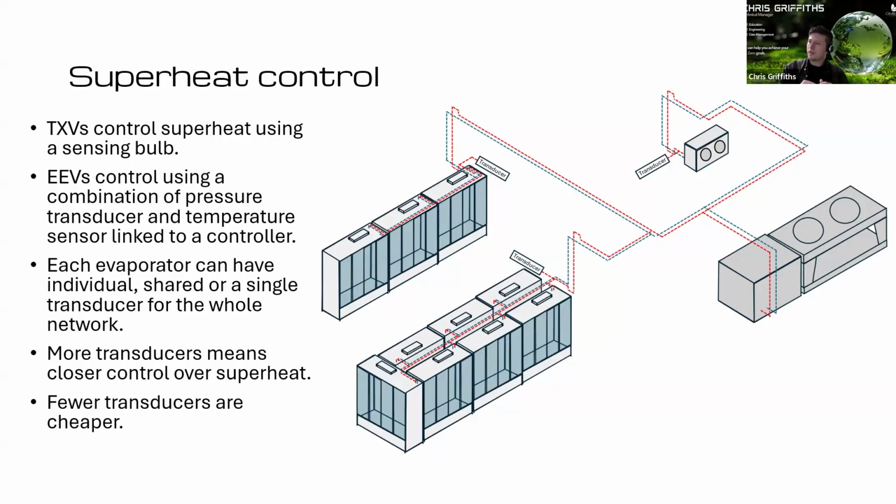Trying to think what else you'd have. Sort of seeing local low superheats on those fixtures that are iced up, so fans tripped or something like that.